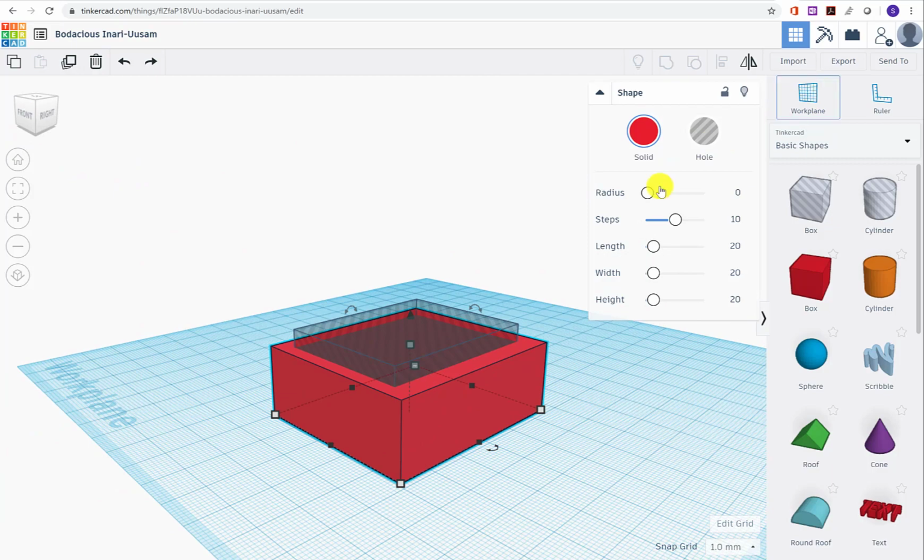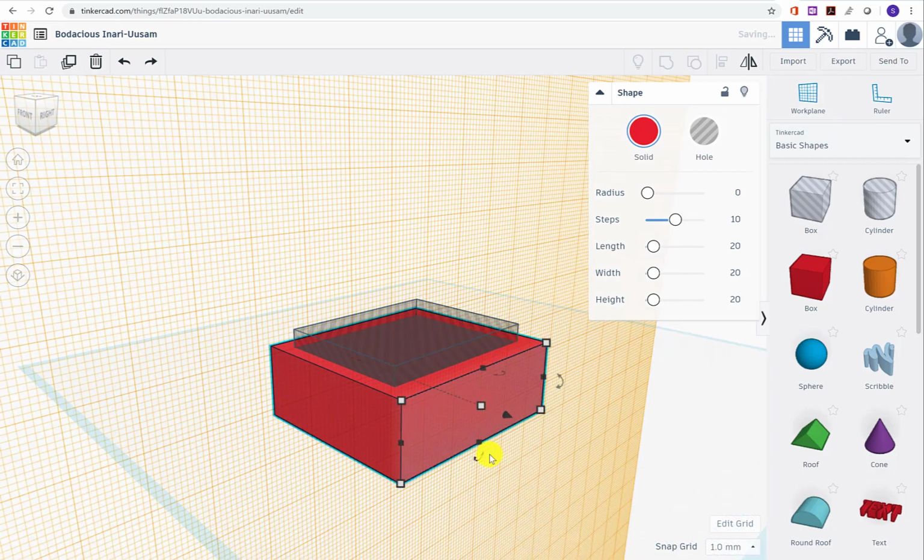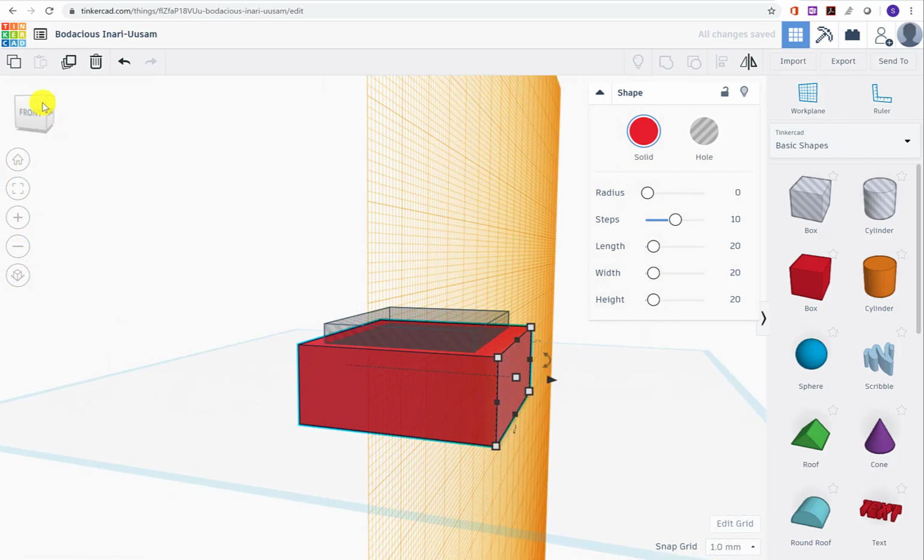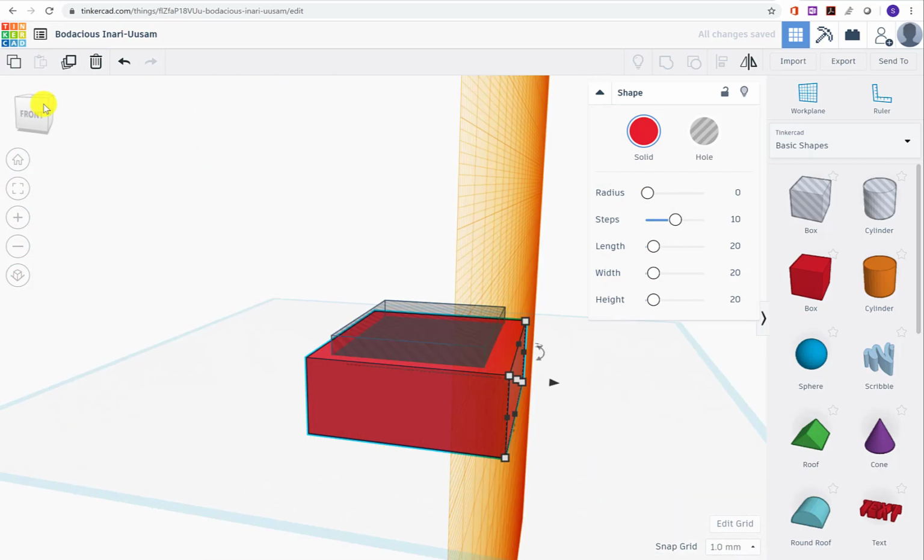And the reason I showed you the work plane before, so if I went from the side again, if I now see where that little cone shape is, that's now relative to this work plane. So it's pulling it from that side. So if I move, again, I always pick the wrong one. I want this one here. And you can see that I'm moving there. And that means it's 3 mils from that work plane.